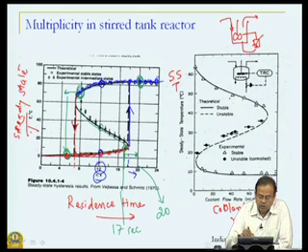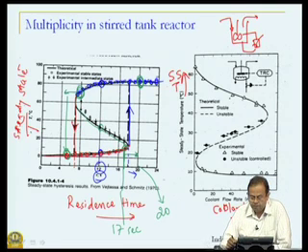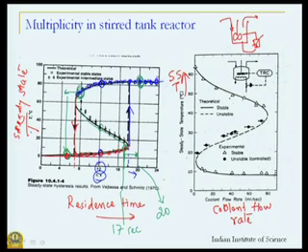So, steady state temperature in the reactor is on the y axis. So, let us try to do an experiment where we start with a very high value of coolant flow rate. Now, when you have a very high value of coolant flow rate, you can expect the temperatures to be lower, and this is what we get. So, let us now do an experiment where we started with this point and then went on decreasing the flow rate, wait for some time for steady state to be attained and note the temperature, and this is what we will see if we keep on decreasing the coolant flow rate.